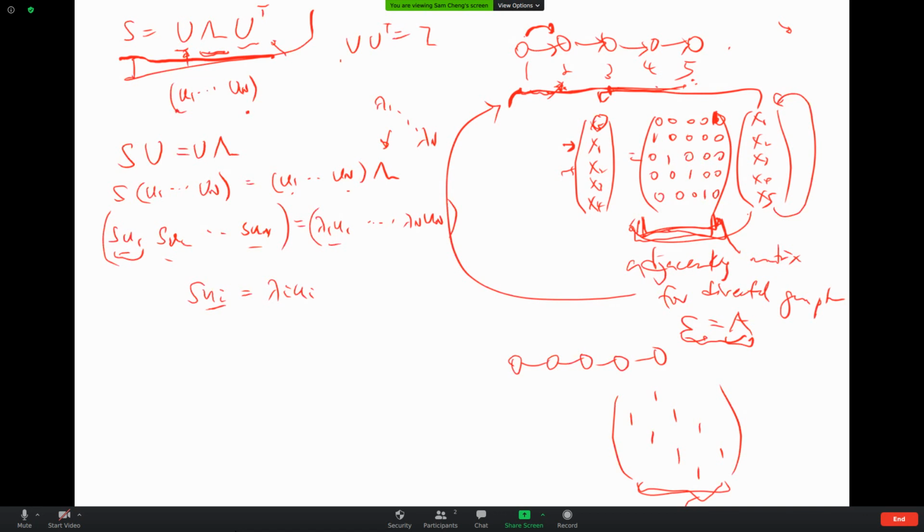So now the Fourier transform in this case will be, I'm going to do a projection to this Fourier basis here, right? So if I have a signal, let's say this vector is just x here, I call it vector x. Then I basically have a Fourier transform. I have x and do a projection to each of the bases. So I have x and U I, to get the I coefficient of the Fourier transform, or I can just write it in a matrix form. So this will be U transpose times x. U transpose, because it's U1 transpose up to U n transpose, times x. This will be the inner product for that.